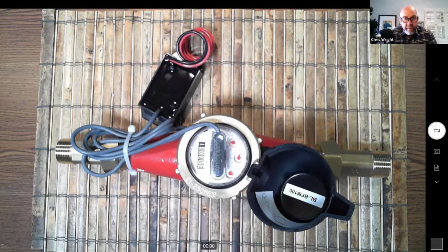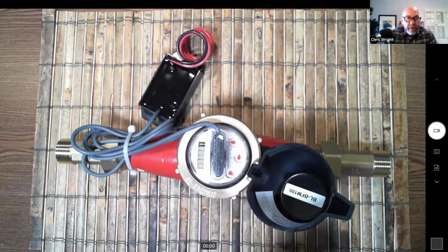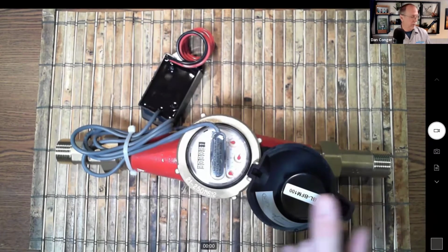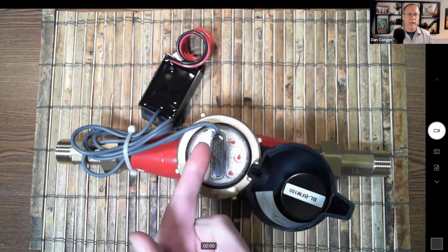Yeah, if you've got a community where you've got mainline for common areas, and then you've got a secondary mainline that's going on to a private property, and you want to account for the water that's being used on that property off of your mainline, that's a great unit to install to do that. So essentially a sub-meter, right? Yeah. And for my water conservation days, that's all we had, right? We just had this visual representation where you could go out and read it. But now we've got the best of both worlds.